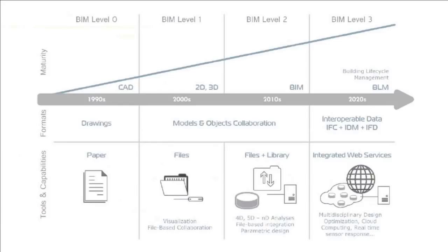Yeah, on the hardware side, a lot of these things are benchmarked. If you go to Vectorworks, they'll show the minimum operating standard. I think it's probably more a graphics card kind of thing, particularly if you're going to be doing a lot more of the 3D design and you want to move around within the model and not have any latency. RAM is going to be leveraged mostly when you're processing the model or doing the digital terrain modeling, which we didn't even talk about, but that digital terrain modeling is also in that BIM environment.